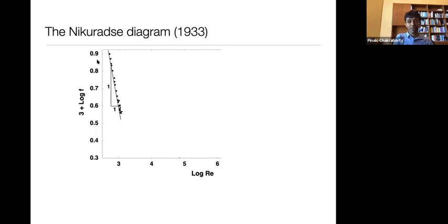Around 2000 Reynolds number, there's a sudden and abrupt transition to turbulence, and friction, instead of decreasing with Reynolds number, starts to now increase with Reynolds number. And in this initial region of increase with Reynolds number, again to experimental precision, all of these 6 different curves for 6 different roughnesses, the friction curves, are all collapsed onto a single bundle.